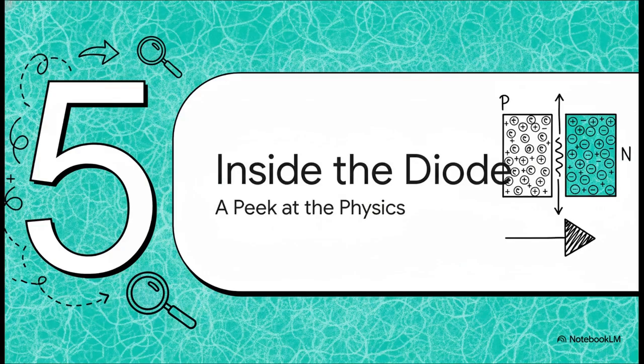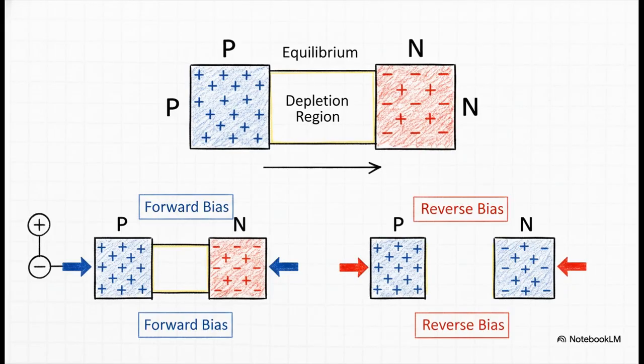Okay, so we know how a diode acts, but why? Why does it have this bizarre one-way property? To answer that, we have to zoom way, way in and look at the physics of what's called a p-n junction. So at its heart, a diode is made by mashing two slightly different types of silicon together, a p-type and an n-type. Don't worry about the names. Just know that where they meet, they naturally create a little barrier that stops current from flowing. We call this the depletion region.